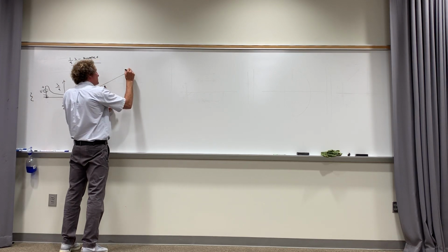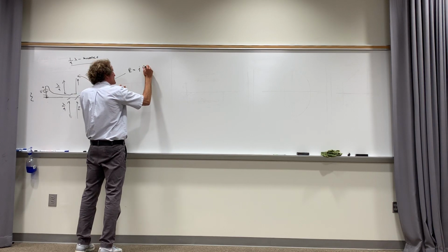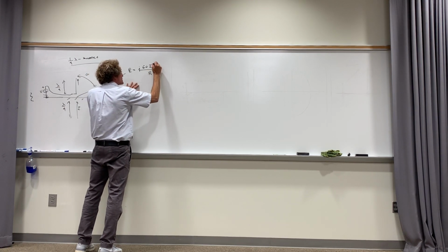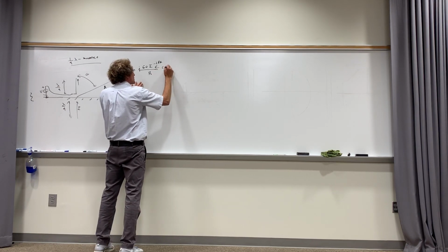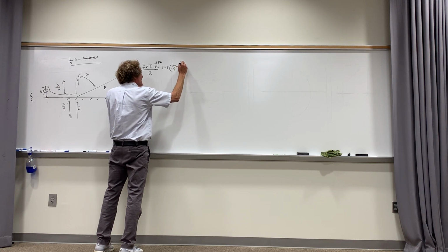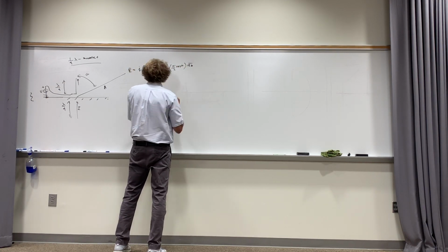The E field would be equal to j 60 I over r, times e to the minus j beta r, times cosine of pi over 2 cosine of theta over sine theta, in the a theta direction. That would be the electric field.